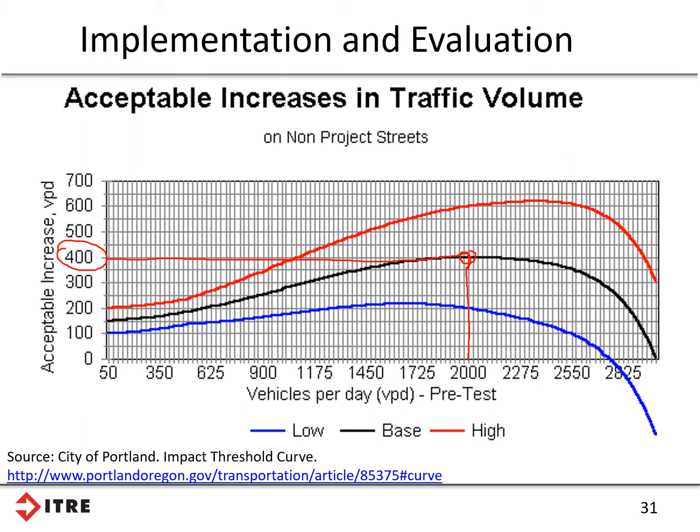So there are a lot of advantages for traffic calming, and again, all this is under the umbrella of speeds and speed limits. It can reduce vehicular speeds, it can reduce the number and severity of collisions, encourage walking and cycling, and reduce the dominance of vehicles. But it can also have some disadvantages.